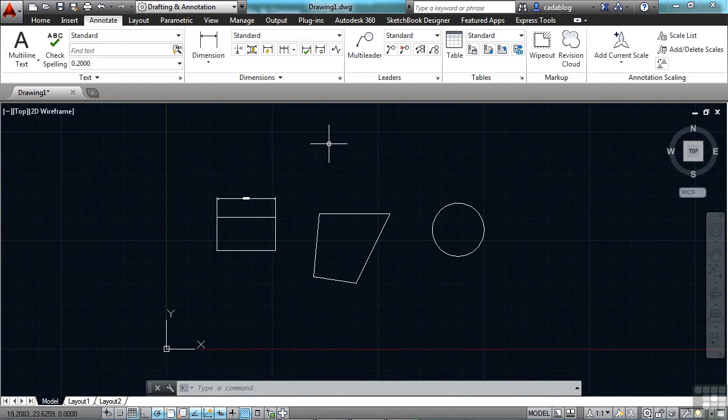So this big open area on your screen right here is called the drawing area. This is where your drawing objects will go. As you move the mouse around, the crosshair moves. Left and right, it goes left and right, up and down, diagonal, in a circle, etc. When you move into the interface area, the crosshairs turn into an arrow. That's up here, your interface area. And this area, which you're going to interface with the software, has different sub areas and different names for them all.